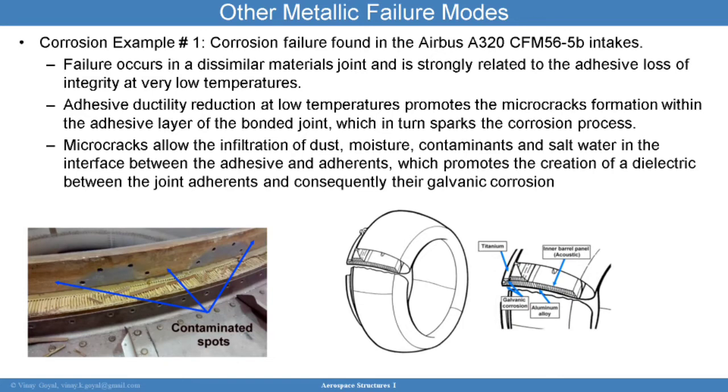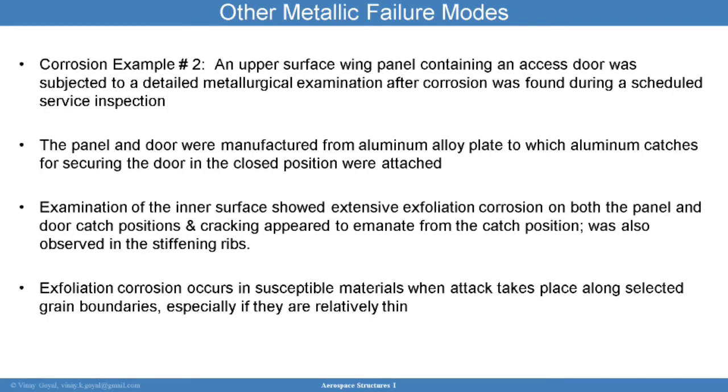So galvanic corrosion is frequent when you have these types of materials interacting in an environment. And so again, it's very important to understand that while galvanic corrosion may not require special conditions, damage can occur locally when you have two materials that are not really compatible in terms of electrical compatibility. And we'll be talking about that later on, how to come up with materials that are compatible.